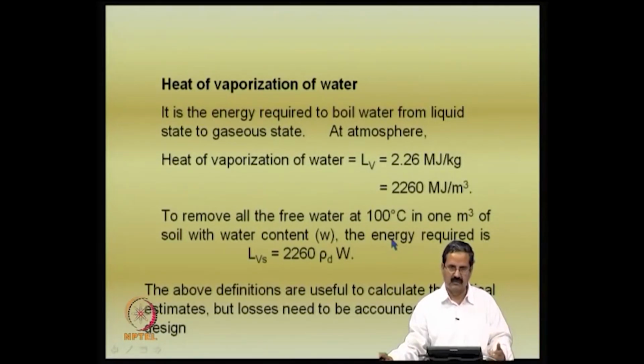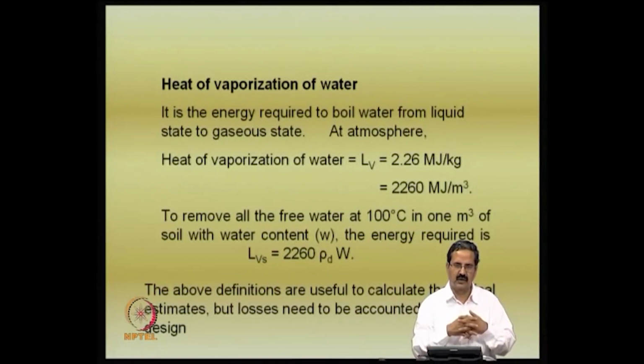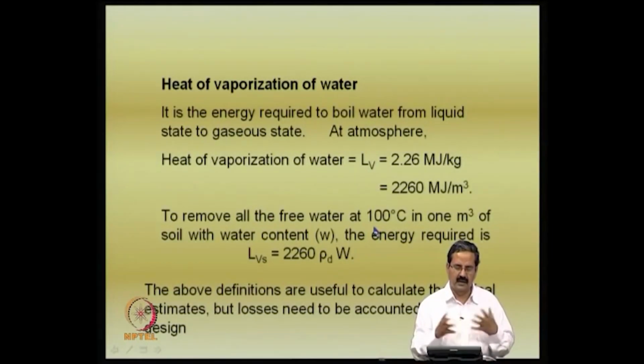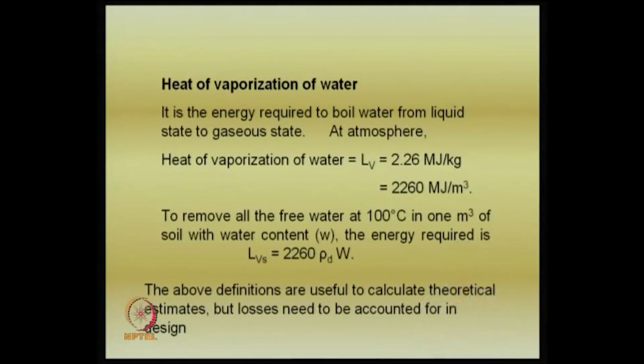Both are possible, whether you supply heat to the soil so that it becomes very stiff. When the water is removed and the soil is heated to a very high temperature, say 400 degrees centigrade, that is what people used in the olden days; the burning of bricks is a classical example. You are trying to use this temperature to bring all the particles together, make a very good soil structure, so that they are very strong.